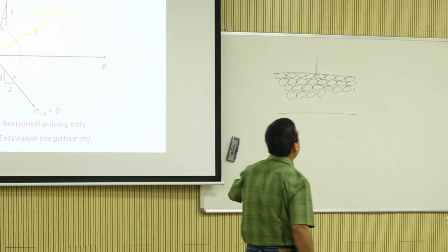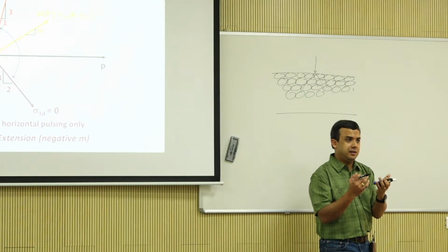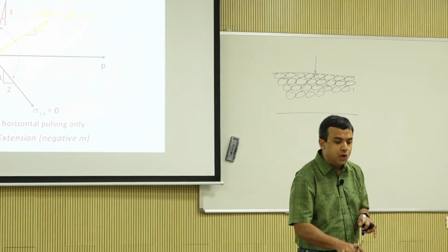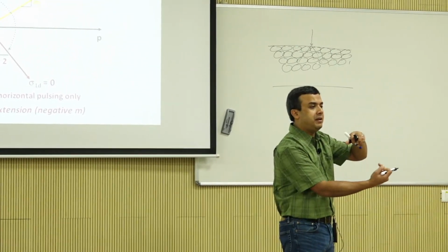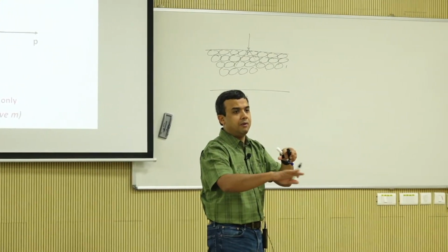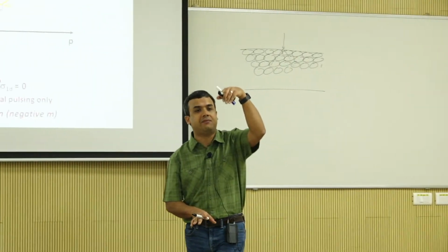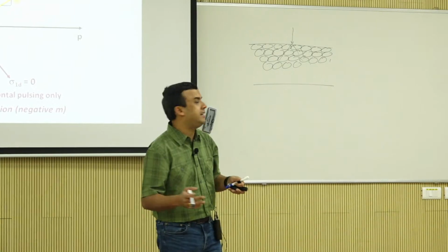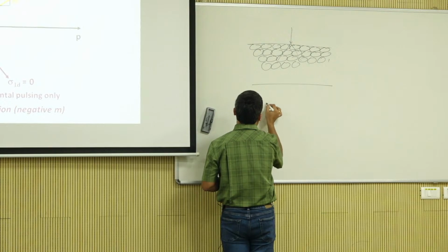But what I introduced is that because aggregates orient like that, it is still axisymmetric around the horizontal plane. So it's similar on the horizontal plane, but if you compare vertical and horizontal, it's going to be different. That is the reason we use the word cross anisotropy.